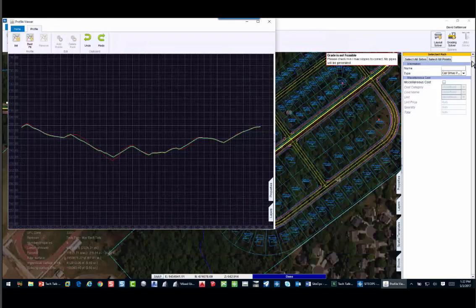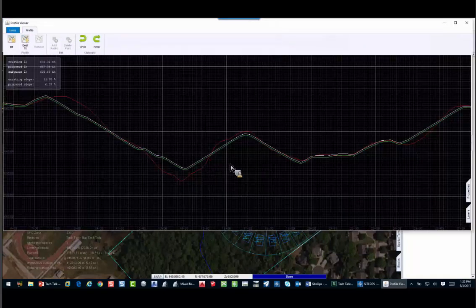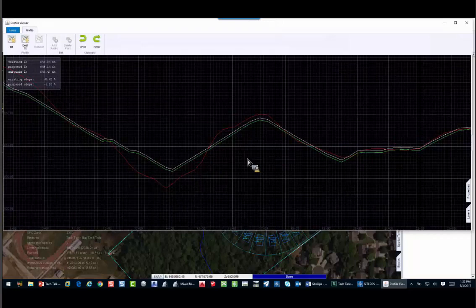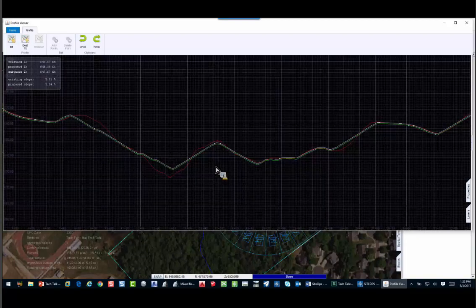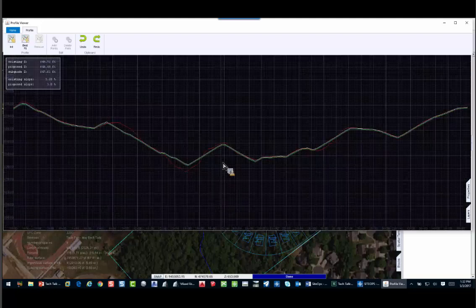And it's trying to apply everything it can. So for example, if we look at this roadway section, I just took a profile. Red is existing, white is top of roadway, green is subgrade. We do go to subgrade if you tell it the material thickness. But here's a problem. This road is not drivable. It's garbage. So I need SiteOps to go in basically like a second level of optimization.